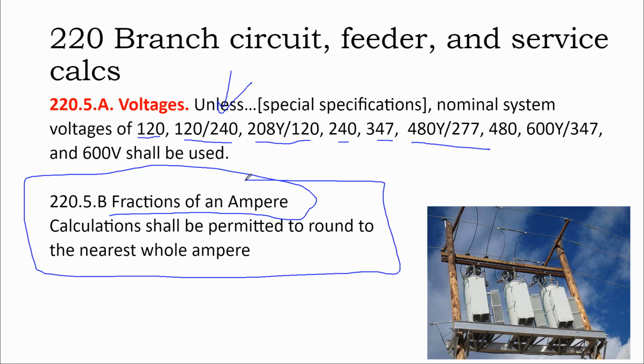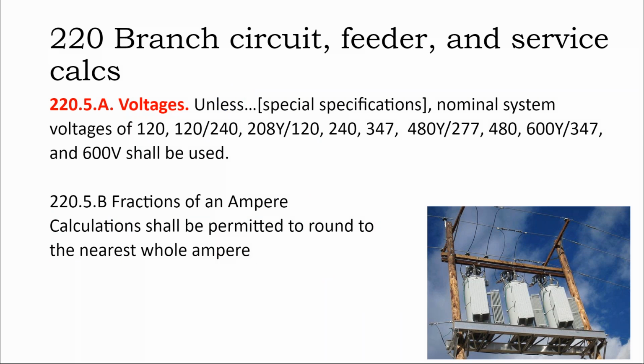It's where we're overestimating the safety requirements in order to enable just regular electricians to pick out the appropriate material without being engineers. And similarly, fractions of an amperage can be rounded to the nearest whole amp. Now, on a label, when it says you have to list the volts and you have to list the amps, you don't list the decimals. You just stick to whole numbers.